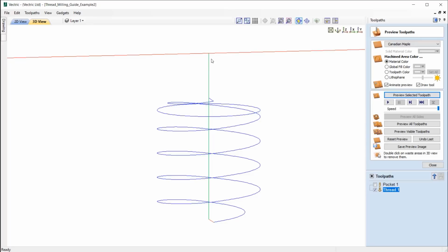Okay, so what's happening? Tool is going to drop down. Okay, it's then going to lead in where it's going to move the tool, or in particular the tooth of the tool, into position at the start depth, where it will continue around in one complete flat circle to create a chamfered top, where it will then spiral down until it gets to the bottom, and then it's just going to do a lead out where it's then going to be retracted, and then it will just leave that hole and move on to the next one.